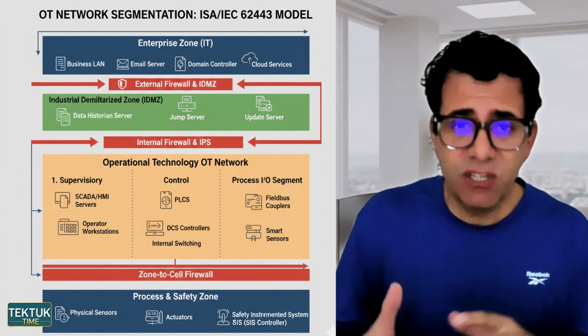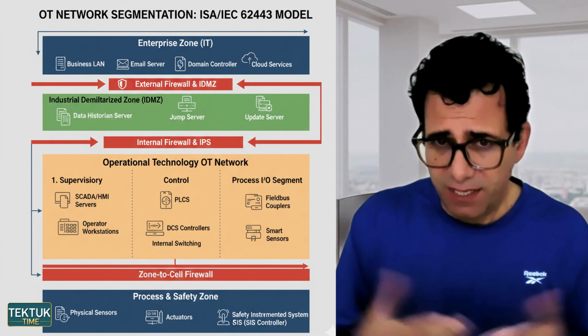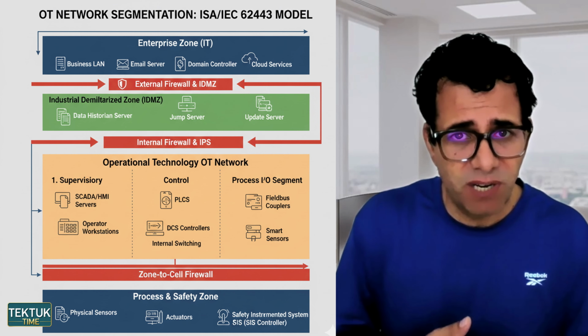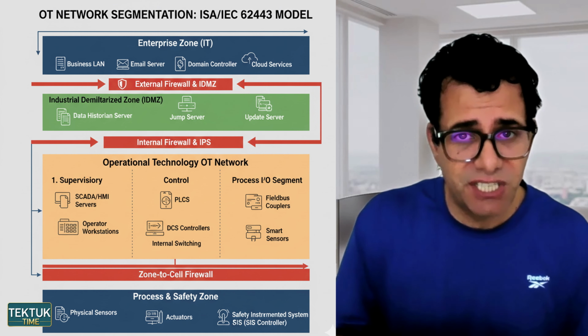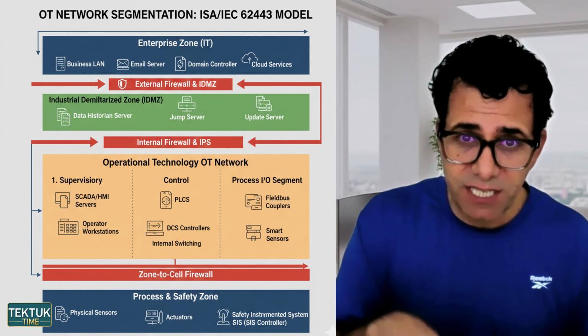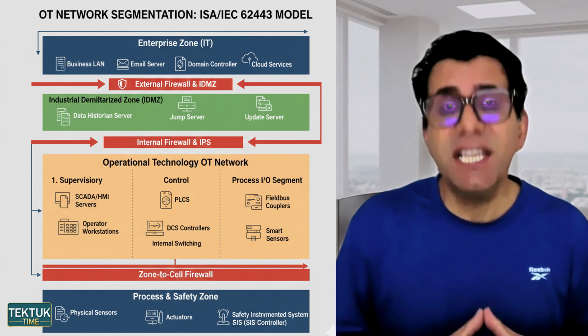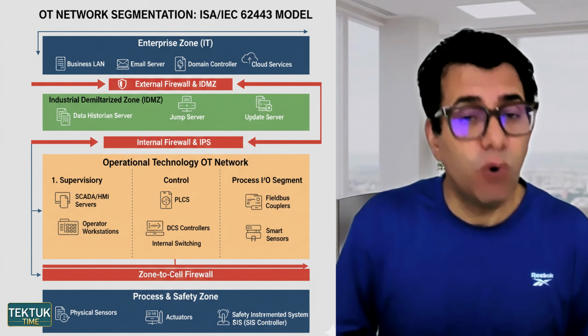Even if they get into the network, the attack and the compromise are going to be limited. The damage that they can do is going to be limited to that specific segment. So segmentation and zoning is very, very important in the OT environment.